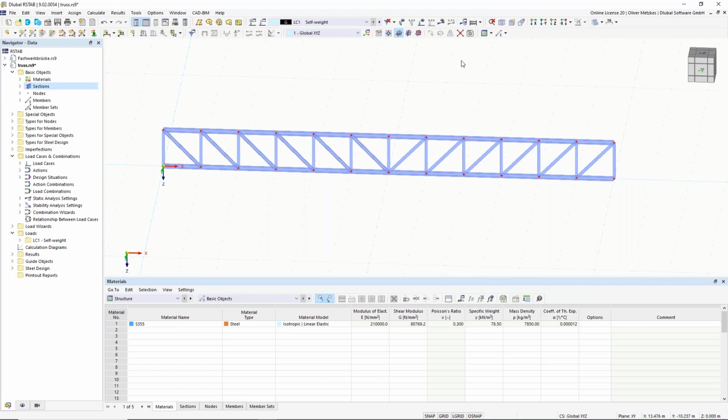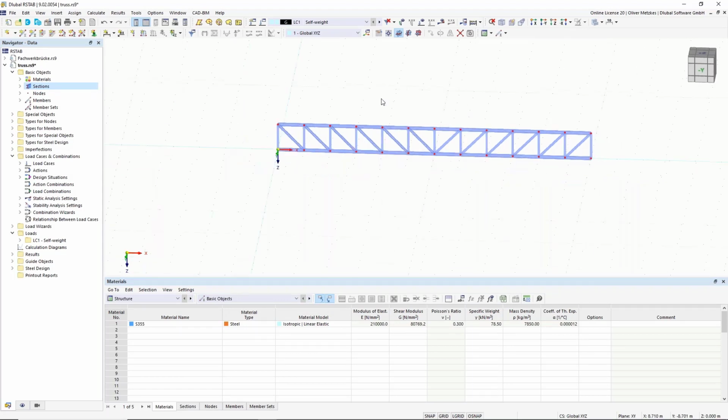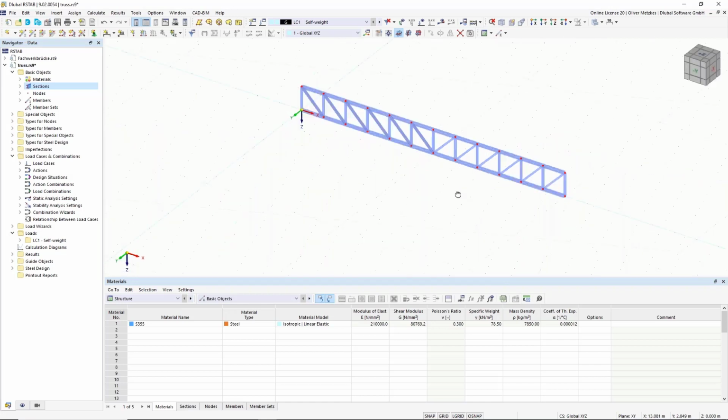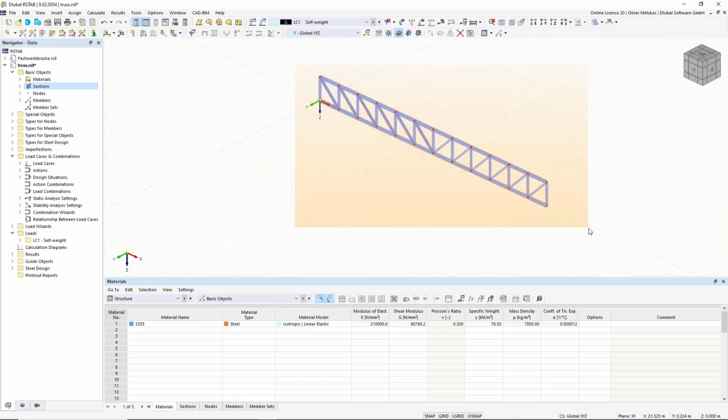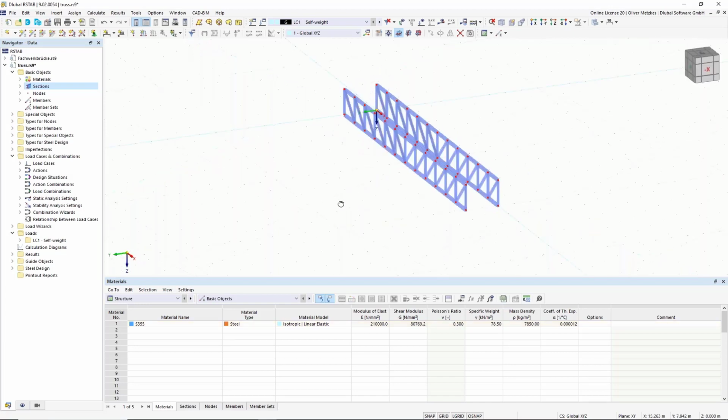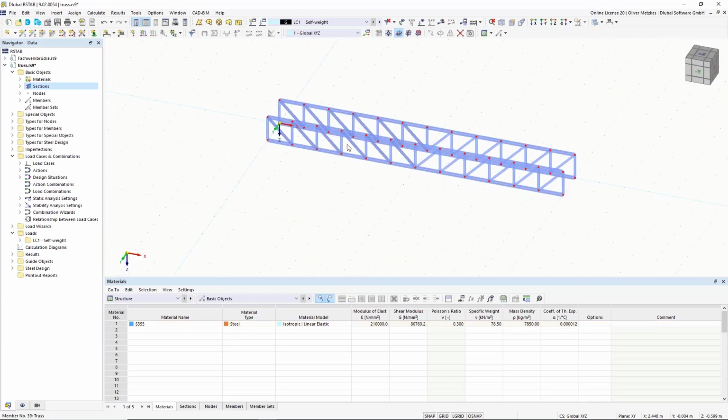Okay, good. So already I have half of my structure here. And now I want to copy it again to have the second half, and I will do it again by using drag and drop, because I know that the grid points in this direction are spaced every 1 meter. So as I want to have 2 meters of width, I can simply pick it again, use the second grid point here, and pressing the Control key, I can release it and it's copied again.